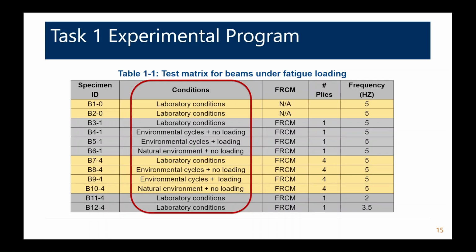If you're familiar with typical FRP systems, we usually say there are three things that we have more concerns with, which are usually temperature, moisture, and stress or sustained loading. And those are the three things for a lot of polyurea-based binding systems that we have to be mindful of, Tg and things like that. So we looked at some similar stuff here.